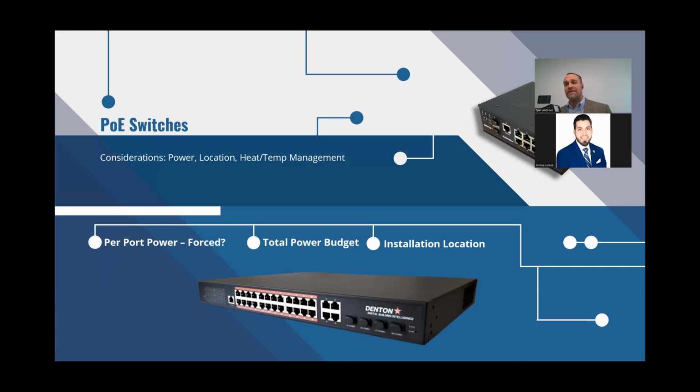Now, having said that, there are differences in 802.3 BT type PoE switches because not all of them will really do what a lighting system needs. And what that is, there's a little bit of a power fluctuation. What we found, some products and some manufacturers don't quite get to the power they need to do before the detection system shuts off that PoE port.